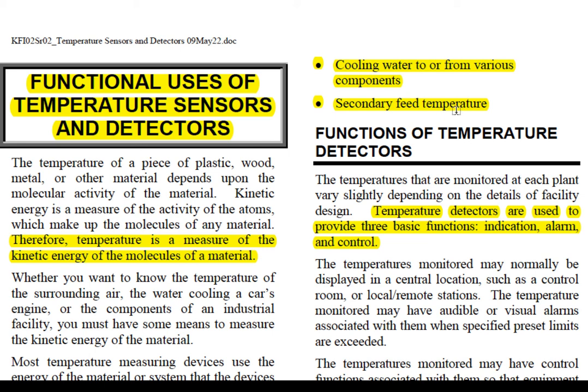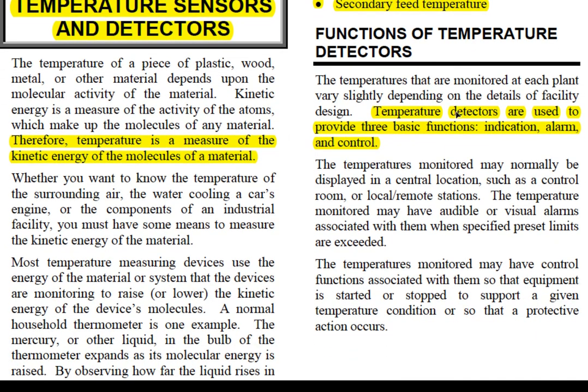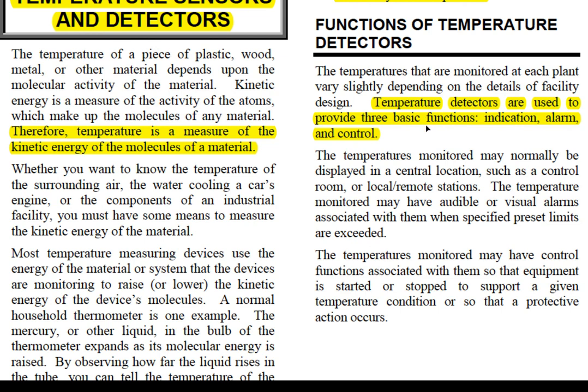And there's a number of different places that we measure temperature over on the secondary side, as you can imagine. Steam coming into the high pressure turbine, water that's being condensed in the condenser, as the water goes back through the feed water heaters, all the way up to the steam generator feed pump, back into the steam generator. Each one of those temperatures needs to be monitored, in addition to each side of each heat exchanger as it goes.